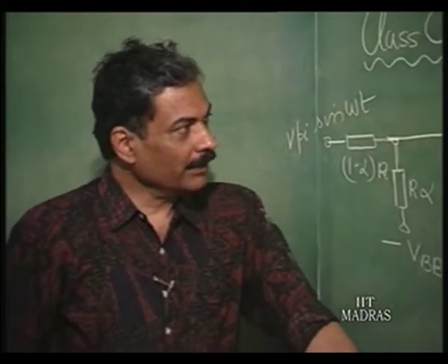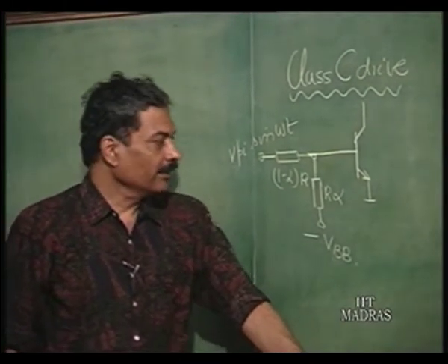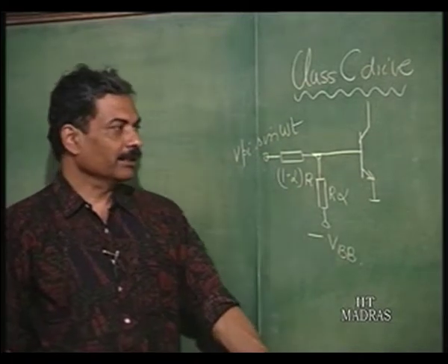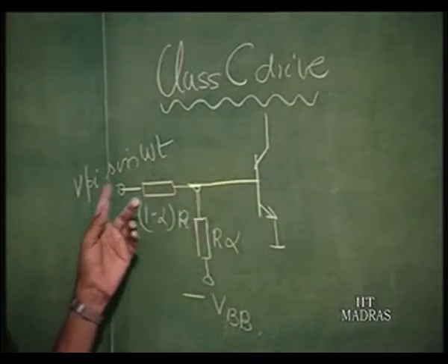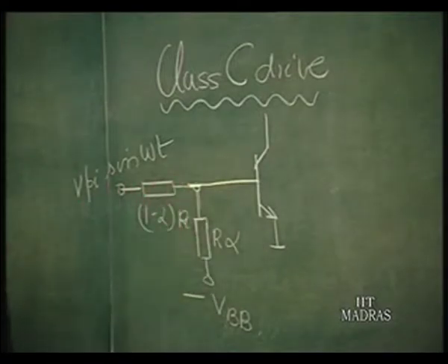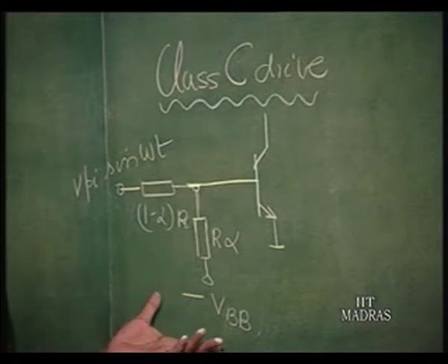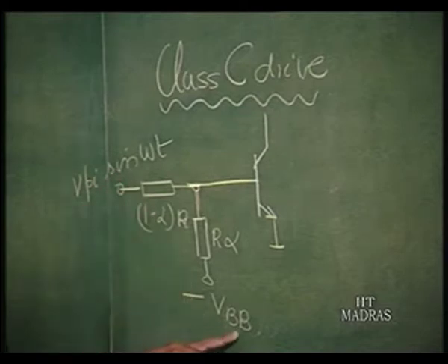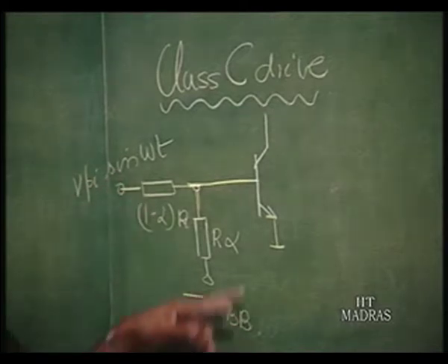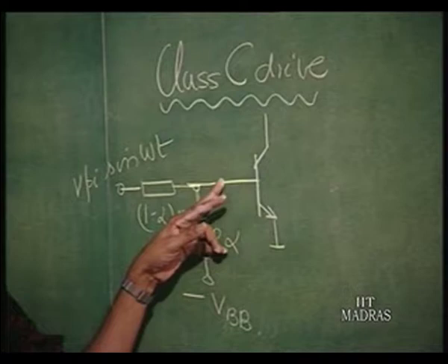In the example just previously chosen, we had for simplicity used the drive in such a manner that the cut-in voltage of the transistor itself could be used for restricting the current drive into the base of the transistor. The more elegant way, which we had earlier indicated in our earlier example, was to use two resistances with bias here, voltage negative in this case, so that this voltage can really determine the angle of conduction.